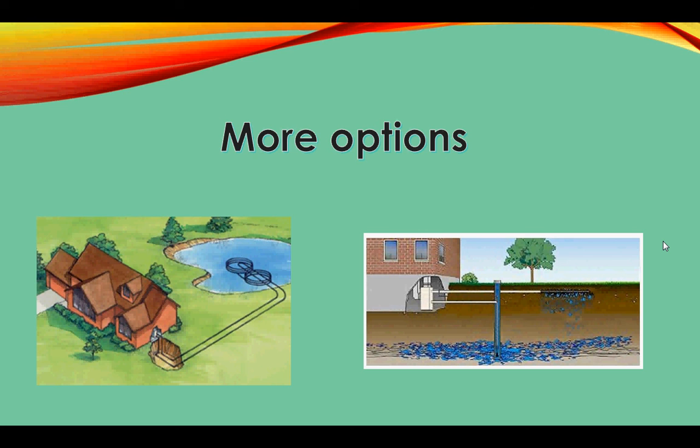On the right is an open loop configuration. For this type, water must be plentiful and of good quality, non-corrosive and non-scaling, as the water is used directly in the heat exchanger. It is important to note that the water returning to the aquifer is the same as the water that was drawn from the aquifer.